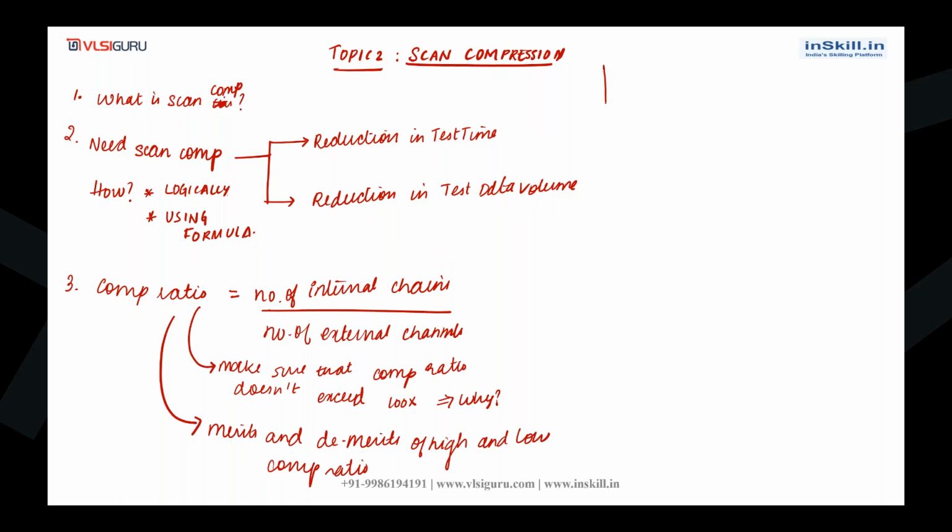After that, we will understand about the EDT logic. In order to achieve scan compression, if you're using Mentor Graphics tools, then you will be adding a logic called EDT logic, which is embedded deterministic test, as we discussed in the previous slide. Inside the EDT logic, you will have various components like the decompressor.